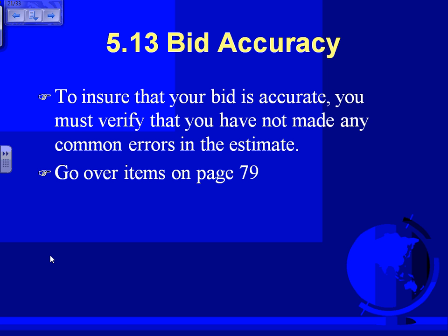Number one, assuming standard grade receptacles when the spec said specification grade. This is a common mistake. Anybody know the difference between a spec grade receptacle and a standard receptacle? A standard receptacle, guys, is 33 cents. A spec grade receptacle is $3. Spec grade is more robust, a better type of receptacle versus residential type receptacles.